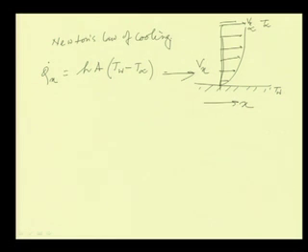As we have seen, in case of conduction, there is Fourier's law of heat transfer. Here, Newton's law of cooling discusses the basic convective heat transfer phenomena. One thing we can also see is that we can write this as (T_w minus T_infinity) by (1 by hA). So, this can be written as equivalent to driving force